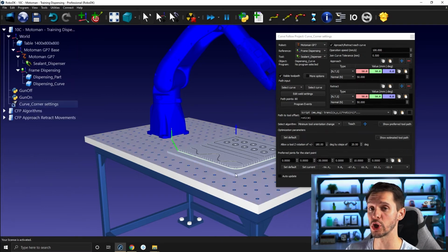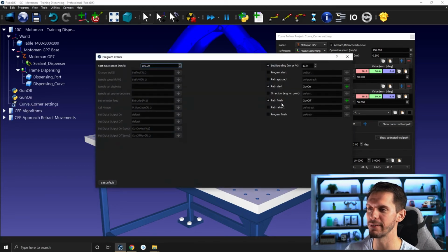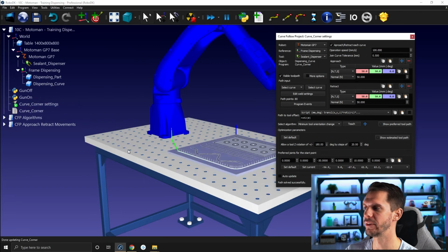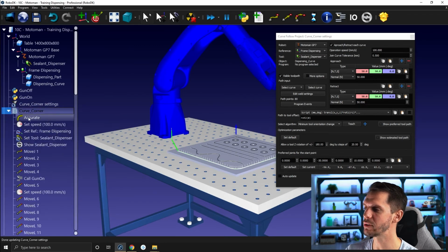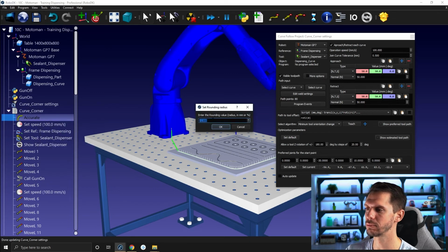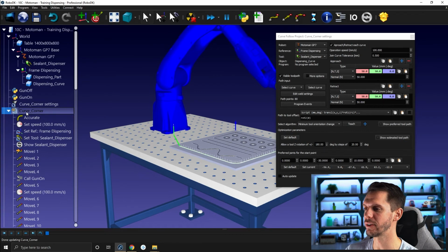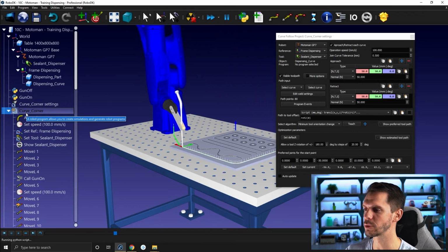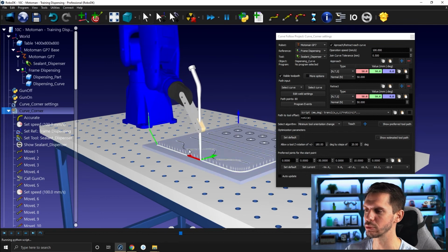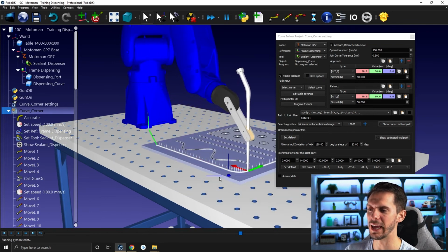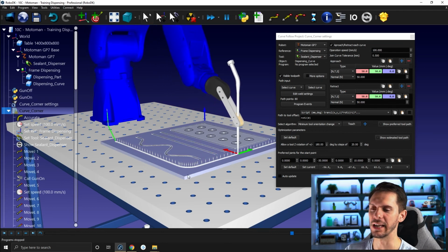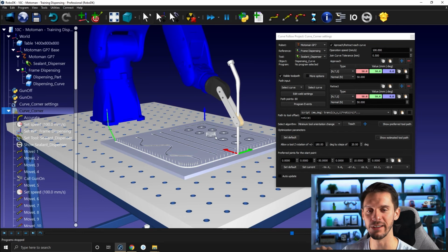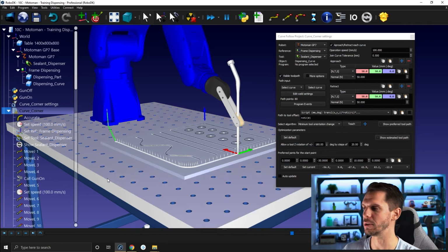If I want to make sure that the robot will stop at each point, let's say that I need it to stop at each point, what I can do is go to the param event and enter -1. If I do that and click OK, update, right click, show instruction, I will now have dimension accurate. So -1 will make it accurate. If I run that here, it will go to each point, and as you can see, it's not super fluid. It's like tuk tuk tuk tuk tuk. This is because I'm stopping at each and every point, and I have to reaccelerate. If you were to look at the velocity curve, it would be 0, linear top speed, 0, linear top speed, 0, and so on and so forth.